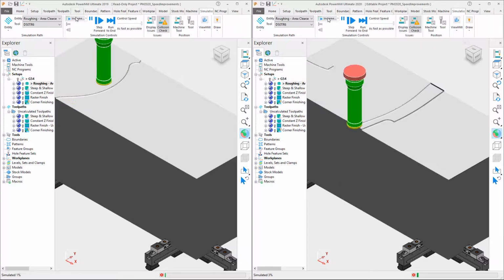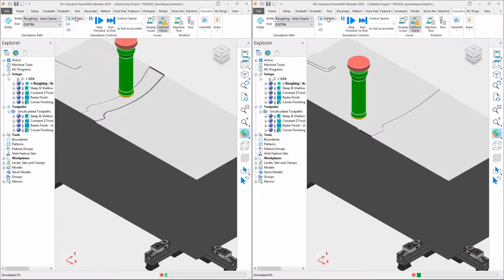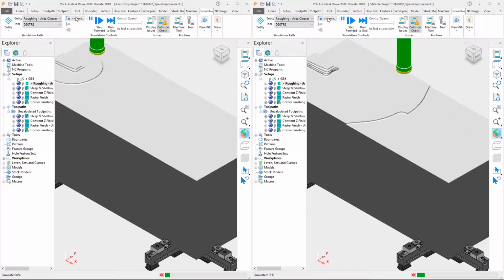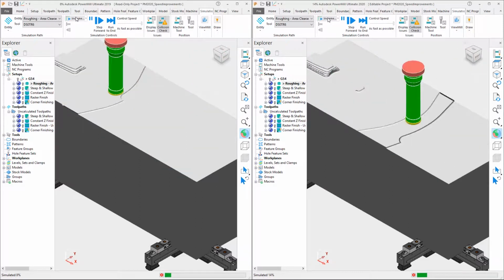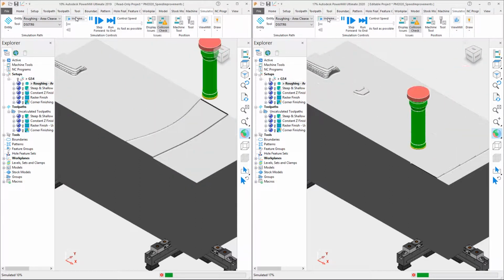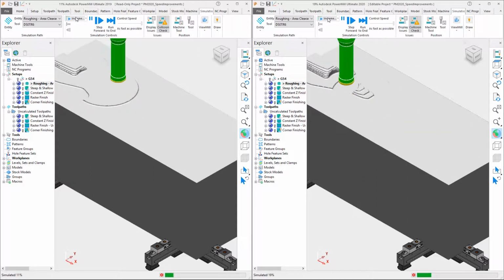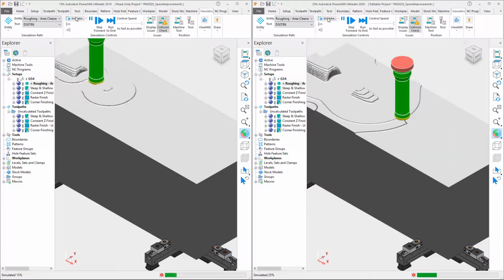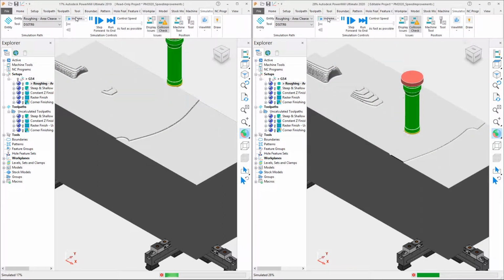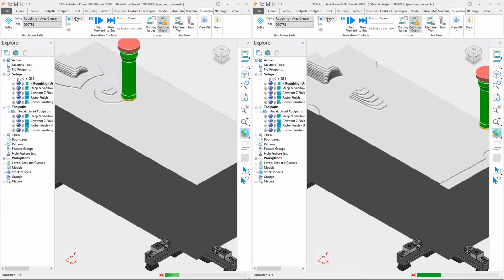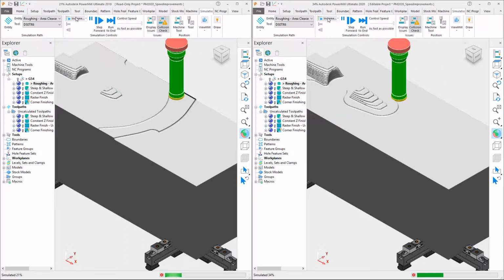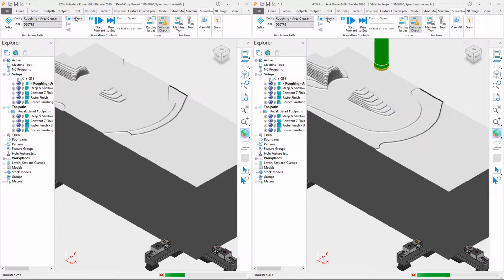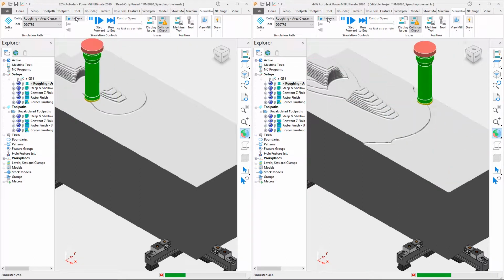This roughing toolpath uses a 50mm diameter tool with a 6mm tip radius. We are using that full 6mm radius as the step down value and have set a step over of 42mm. This toolpath uses an offset style, leaving 1mm of thickness remaining on the part. And since this mold is for a low volume composite part and would likely be made of modeling board, the cutting has been given the freedom to go in any direction.